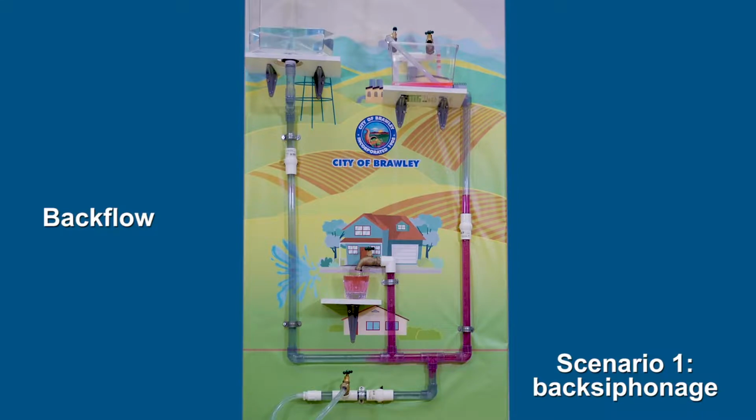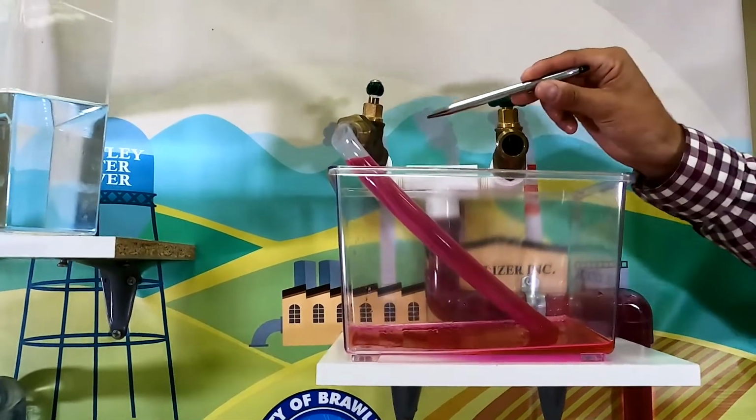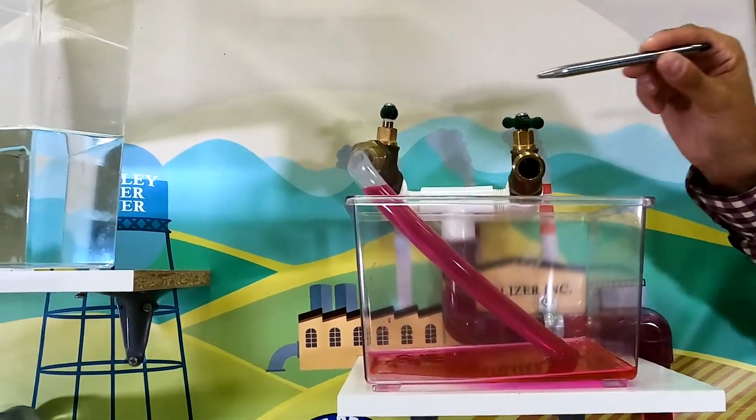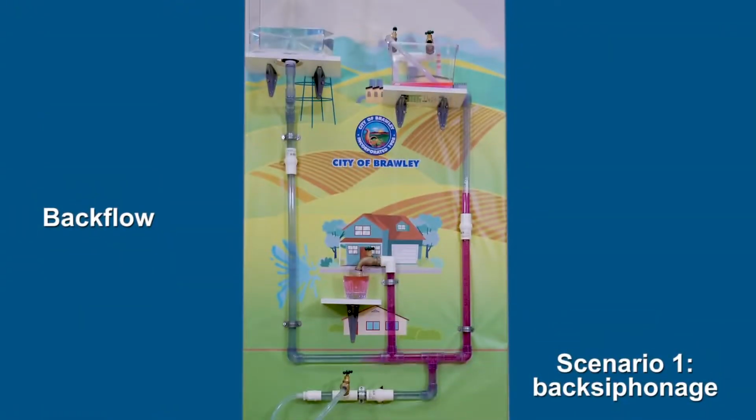In this example, we are lucky because there is only one factory in the area, so the inspector heads straight to the fertilizer chemical works. However, in a real-life situation, it can take longer to highlight where the contamination is coming from. The city inspector immediately identifies that a hose pipe is sitting in the storage system, and this has allowed for the contamination. They inform the chemical company that the contamination is preventable by the use of a reduced pressure backflow prevention assembly, or backflow device.